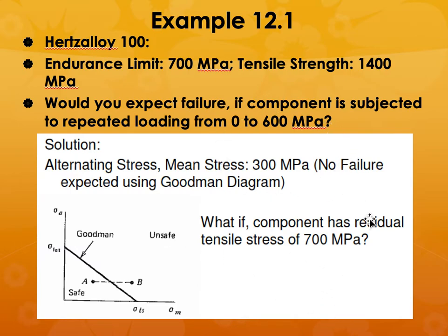You have to add that, so your mean stress will actually go up to 1000 megapascals, which means that it may not withstand that kind of stress level.